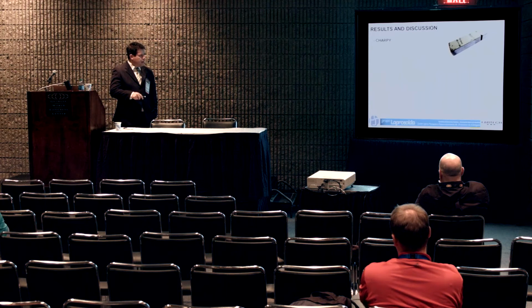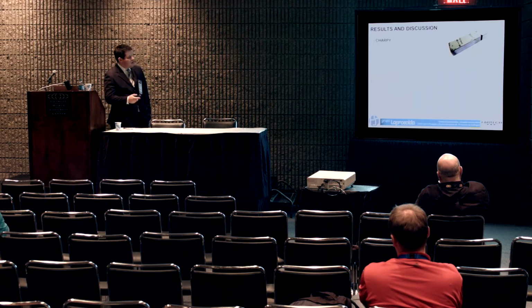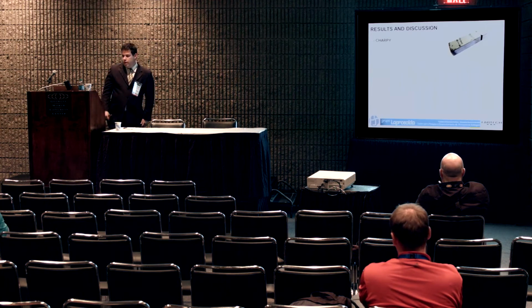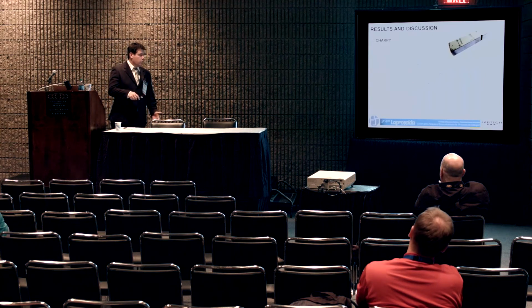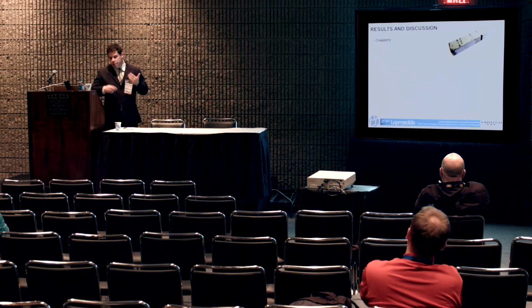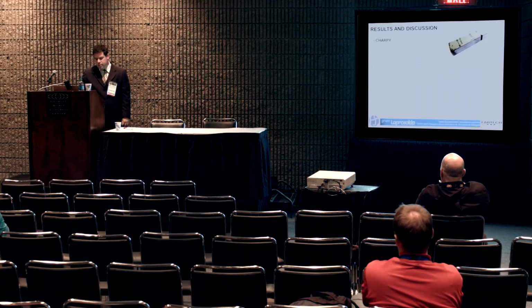So all the absorbed energy is well above 40 joules, which is required in our case. You are here at 150, 100 joules, so way above. But again, because of the material, we did not expect any metallurgical problems. So the V0 Charpy test says that again.